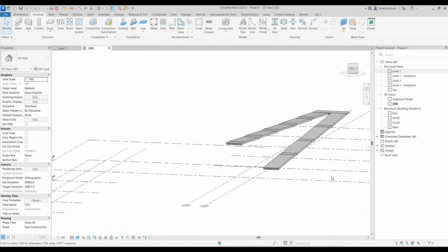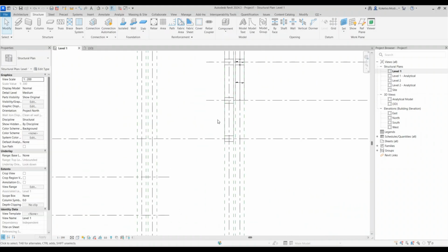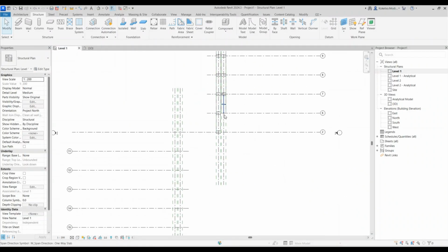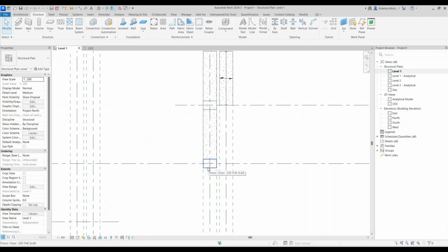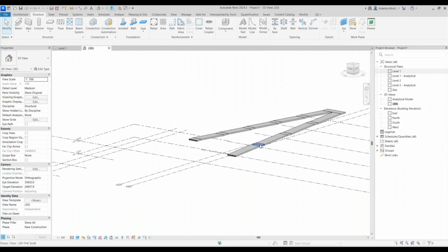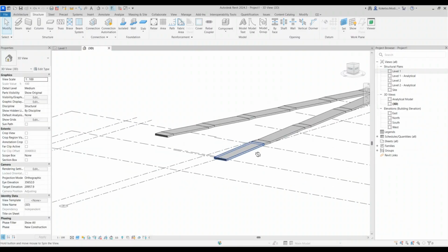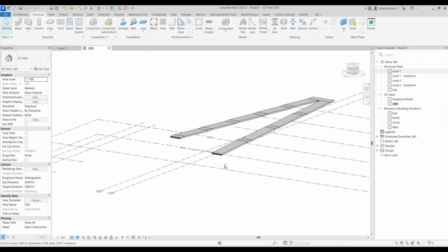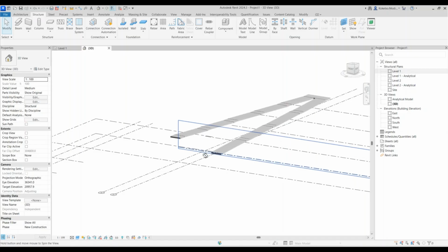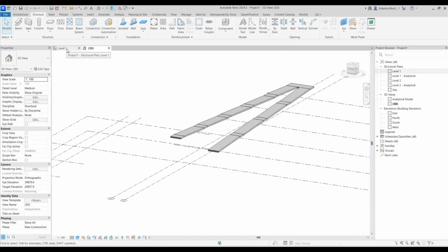Okay, so this is essentially how it looks. I'm only going to solve this side, and then everything else I'm just going to copy, rotate, and place towards the other sides. I think we placed our system families, which are our floors. Obviously, the railings will come after. The next thing is I want to place my loadable families, which are going to be my columns.